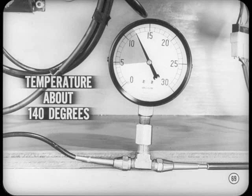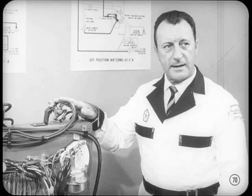Check full opening of the water valve by turning the external vacuum supply up to 12 inches or more. This should increase the air temperature to about 140 degrees. If the valve doesn't make the grade, replace it. Now, assuming that we find the water valve doing what it's supposed to do when the correct vacuum is supplied to it, let's find out whether that vacuum is actually being supplied.